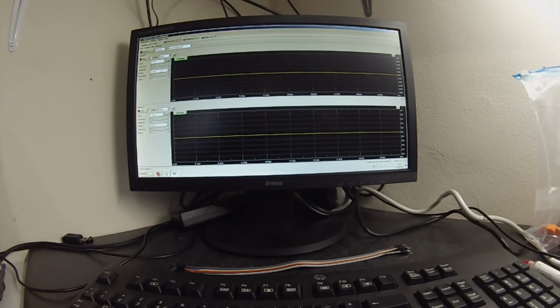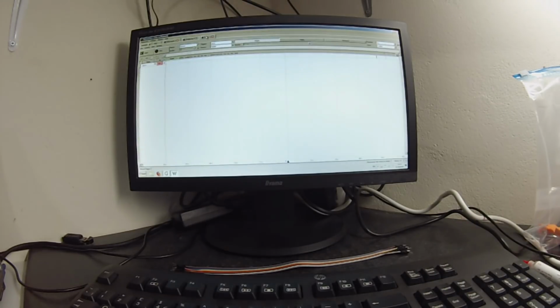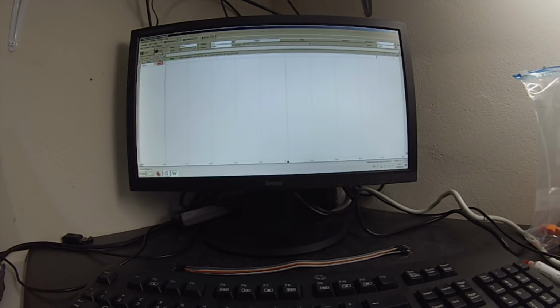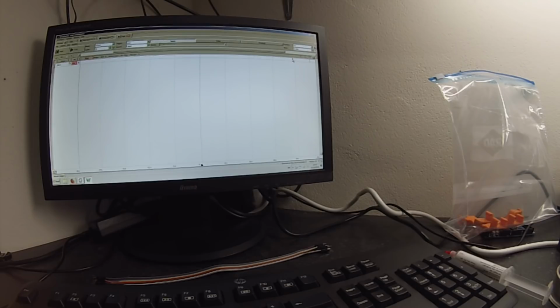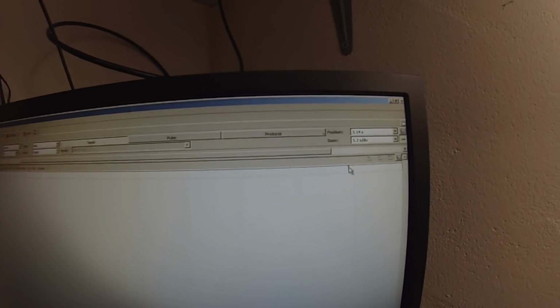So boom, enter. And I'm now going to go over to the logic analyzer, stop it, and you will see here a little dip. Let me see if I can zoom in on that. Not sure if I can. No, sorry, I can't. But let me see if you can see that. But that little dip was our comparator tripping and shutting down the inverter.